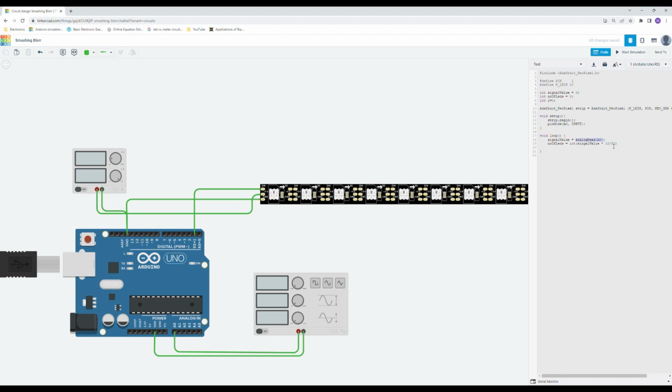So in this case, the 10 means the number of LEDs. The 51 means the value from 255 that we're converting. But most analog signal sources from a headphone amplifier are kind of 0 to 1 volt amplitude.